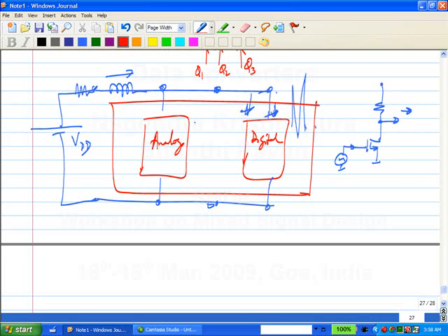One thing you can try is to say that, okay, the inductor is not able to accommodate rapid changes in current. So what you should do is put a capacitor there. It's also called a bypass capacitor or a decoupling capacitor. And what is the job of that capacitor?